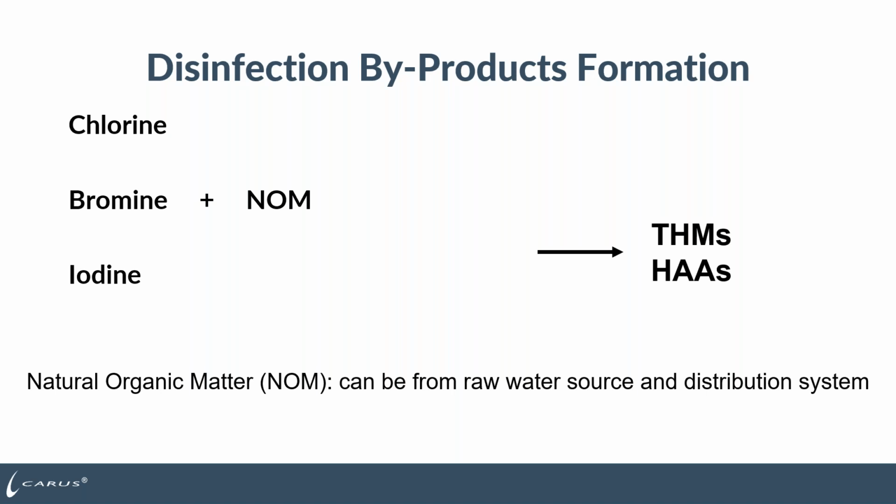So one of the ways to prevent the THMs and HAAs from forming is to react with that natural organic matter, that total organic carbon, with permanganate prior to disinfection so that you don't have as much organics to react with the chlorine when you do your disinfection.